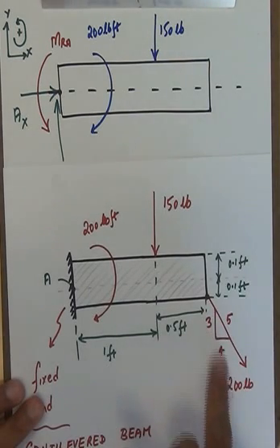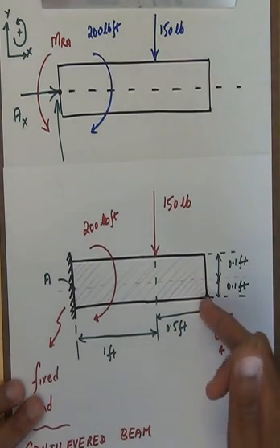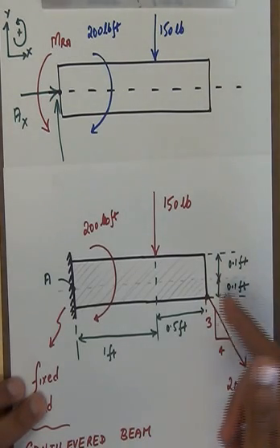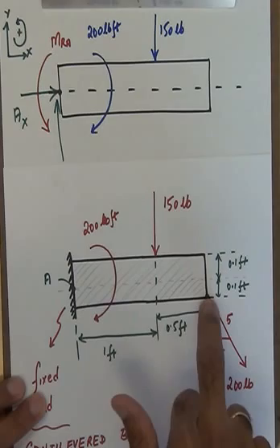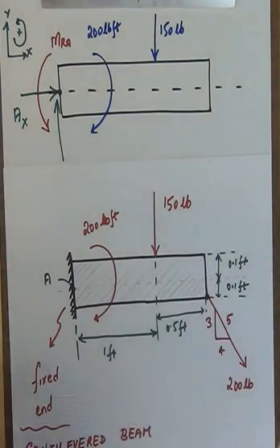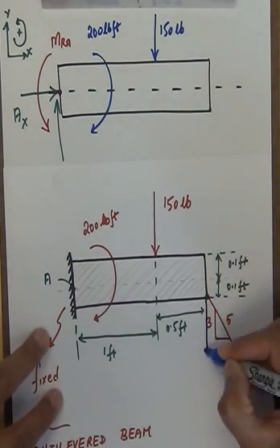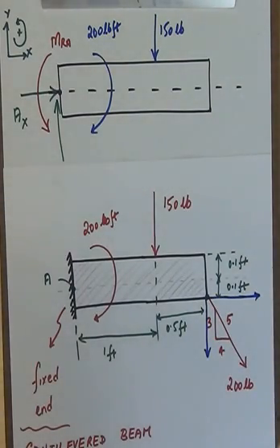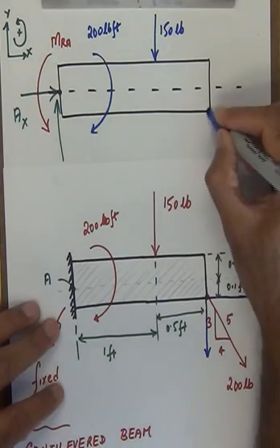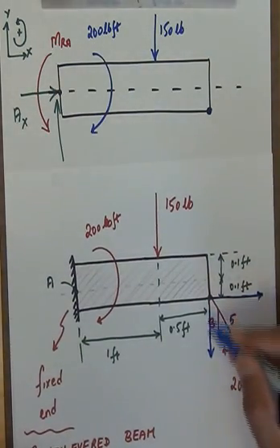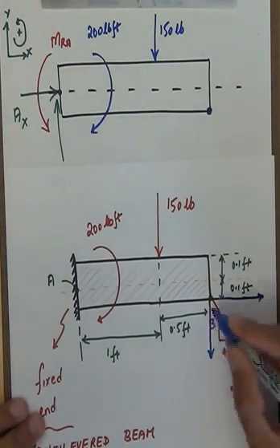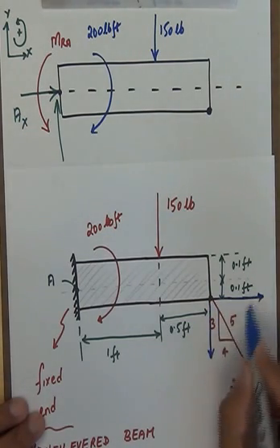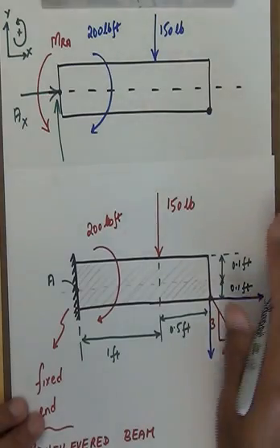The slope triangle is given 3, 4 and 5. So this 200-pound force, I'm going to split it into a component along the vertical and along the horizontal, taking care to start the components from the point of application. So this is the point of application of the force, which means the components must come from those points. So the components must be in this direction and in that particular direction, right? And so here is the point of application. A component along this direction is going to be 200 times 3 divided by 5, which is 120 pounds, and then the component along this direction is 200 times 4 by 5, or 160 pounds.